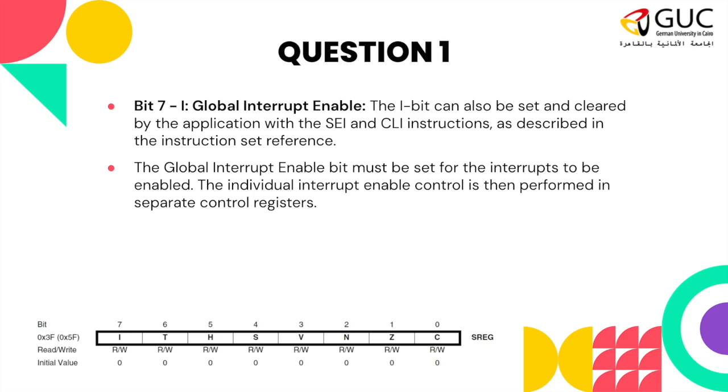However, this is just a master switch to enable the concept of interrupts. In my microcontroller, I have different types of interrupts. For example, I have an ADC interrupt: if I was performing an analog to digital conversion in the background and it finished, it will interrupt my program and notify me that the ADC conversion has finished, so I can do whatever I want with the result and return back to my program after the interrupt finishes.